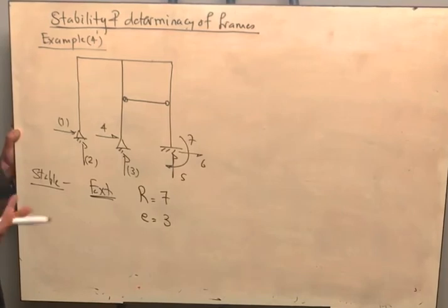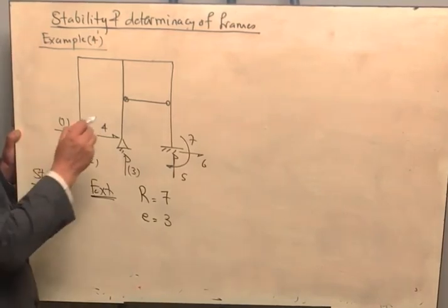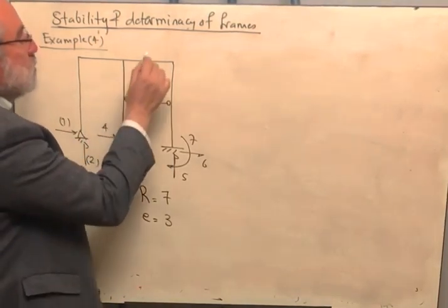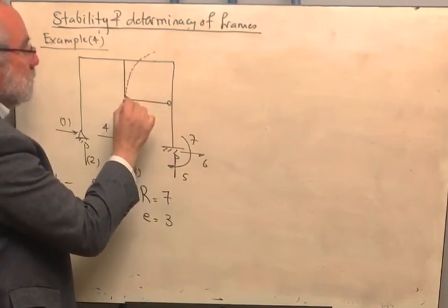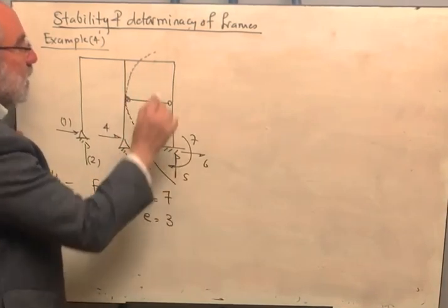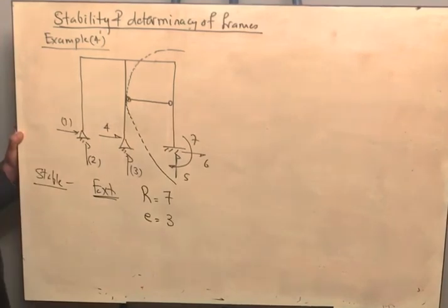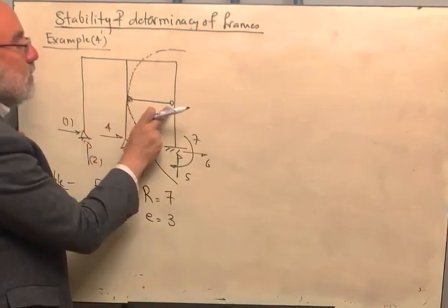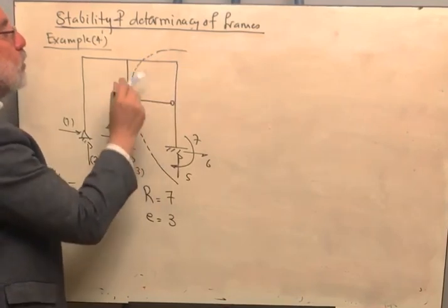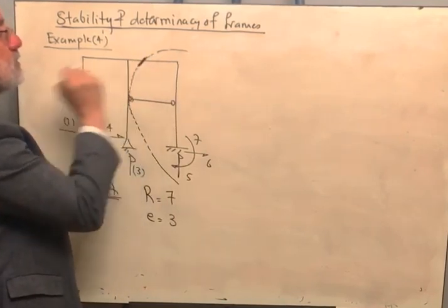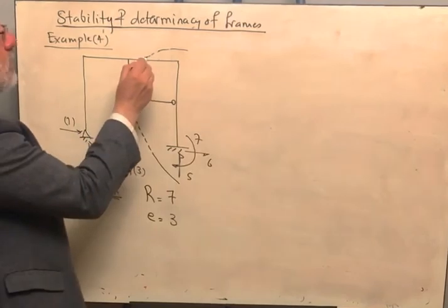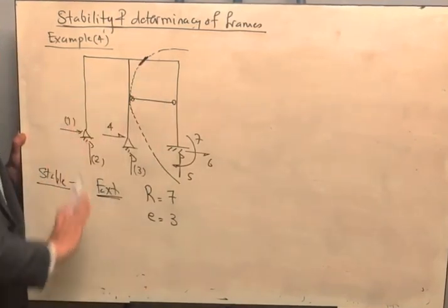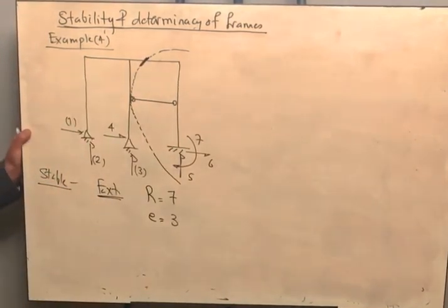Imagine with me how you can use it. Now, you cannot cut like that, but you can cut like this. See, you are cutting like that, so that you can separate the structure into 2 separate parts. You are taking the link member and you are taking this portion. It means that you are cutting here. As long as you are cutting here, let us keep the intermediate hinge to count the internal indeterminacy.